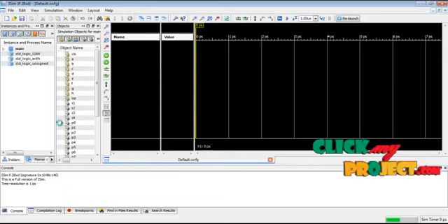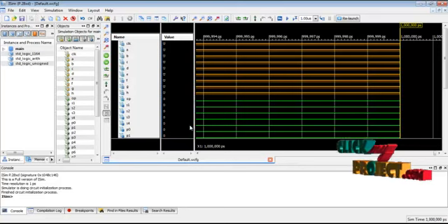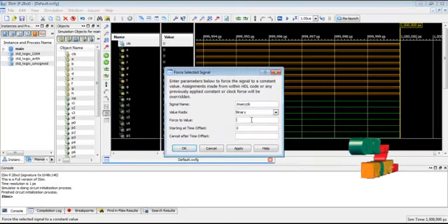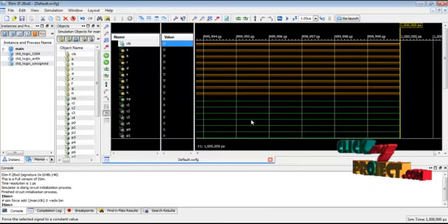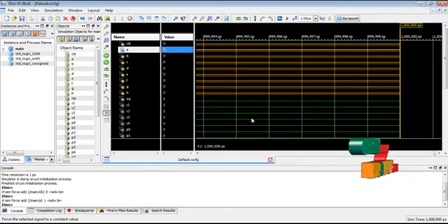Then open the ISim project navigator. This file is used to simulate the results. We apply the binary input for the clocking signal and the D flip-flop data signal for our clock gating architecture.